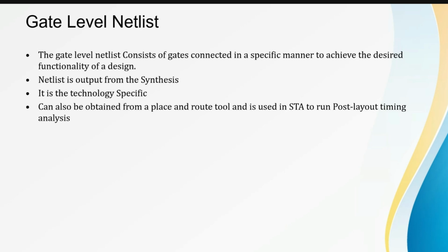That's a post-layout STA. When you are giving the accurate timing, it is in the post-layout STA. For estimation purposes, we do the pre-layout STA.